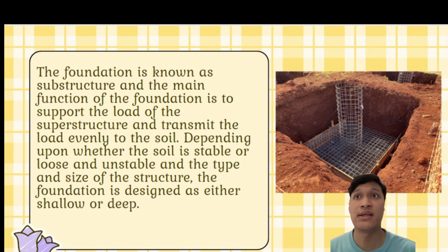The foundation transmits the loads imposed on the structure to the soil below it, and this is why the type of soil is very important for the foundation. Depending upon whether the soil is stable or loose and unstable, and the size and type of the structure, the foundation is designed as either shallow or deep.